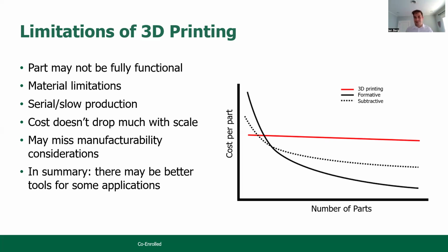Not so much the case with 3D printing: there's the upfront cost of the printer, and then you're sort of stuck with that. And the other thing, when I talk to my engineering students who are trying to create something that would get manufactured later, is that when you rely heavily on 3D printing, you might miss those manufacturability considerations. If you're not doing any of the physical manufacturing, the computer and the machine are, you might make something that would be very hard to get manufactured. And again, there might be other tools for other applications that are better than 3D printing for that.